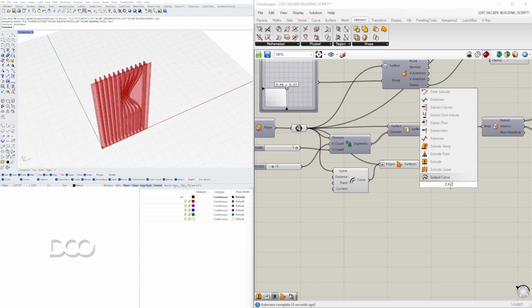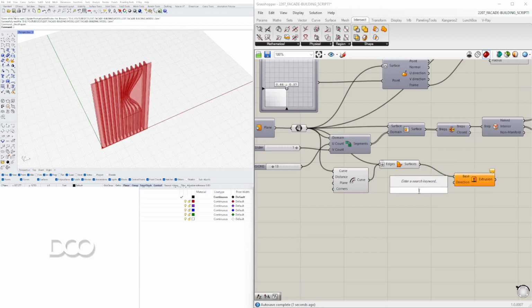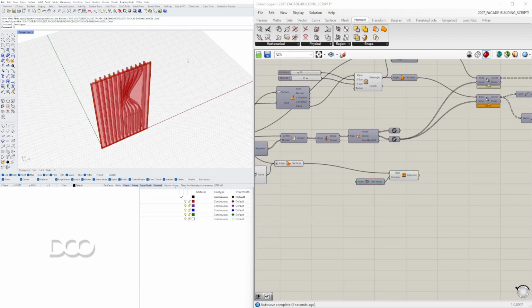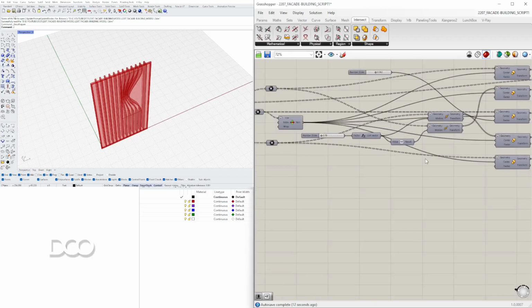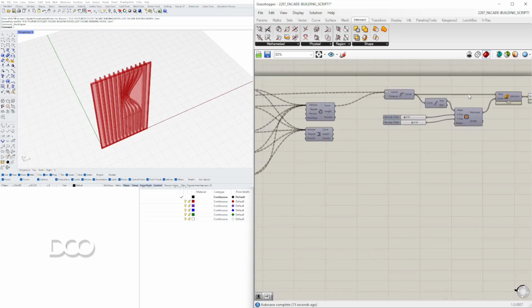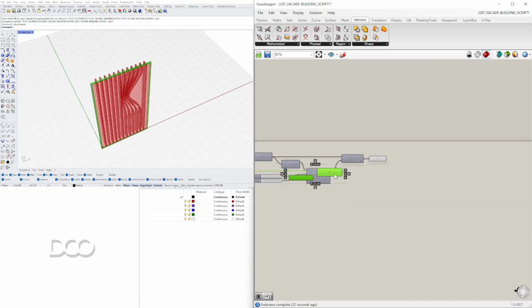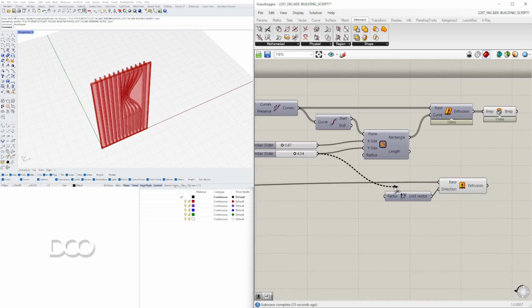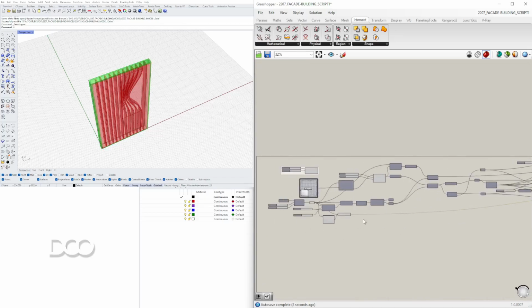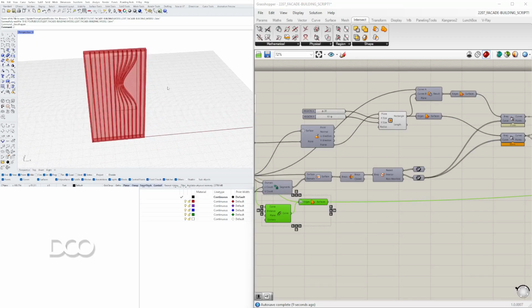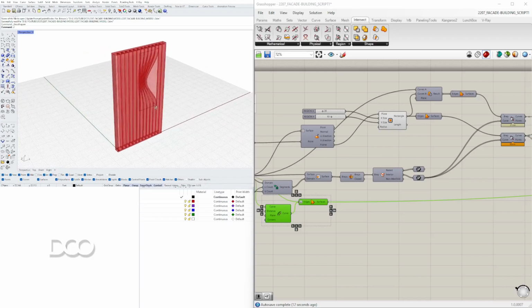Now I'll go to extrude in the Y direction, and I'll extrude it by the depth of this, so 53, or it's not going to be 53, it's back here. 4.54, so we can technically take this all the way to the front. Disable the preview, and that basically takes care of that facade with that portion of the script.